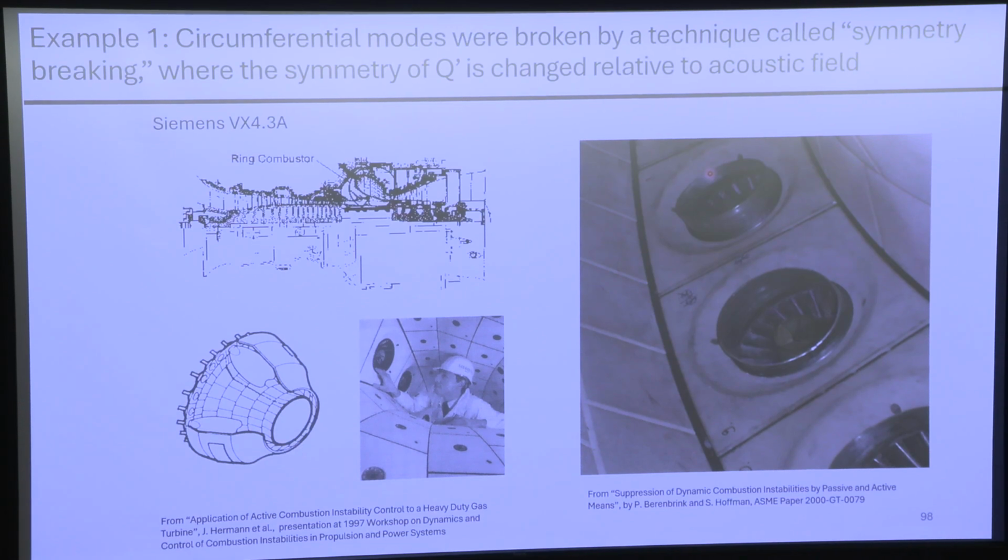What's called your pattern factor, which is the temperature distribution going from the combustor into the turbine, which is all the turbine cares about, is going to look wonky. If you have a nice symmetric pattern factor, the turbine has got 92 blades around it or whatever, and they want a nice, predictable, repeatable thing going on. But now you've got these things all in different directions, so you have to be a little bit more clever about how you inject air and do some of the dilution cooling downstream so that your turbine heat transfer people don't hate you. But it worked. This is in operation. So you just have to be clever about how you do the overall combustor design.